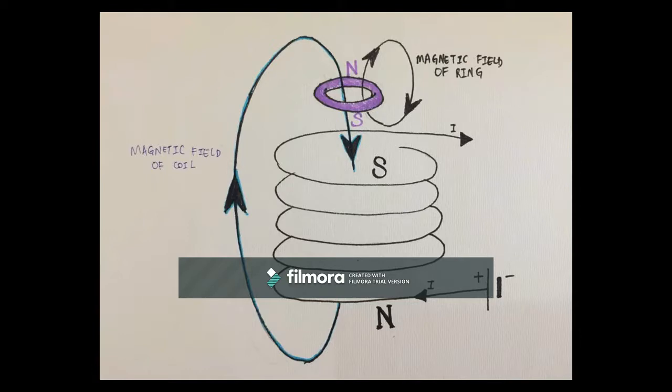Magnetic levitation can be further understood by considering a current-carrying coil. When current flows through the coil, it induces a magnetic field. The change in magnetic field in the coil due to the change in current induces eddy current in the metal ring, which induces a magnetic field so as to oppose the field generating it. The repulsive force of the south-south pole lifts the ring.